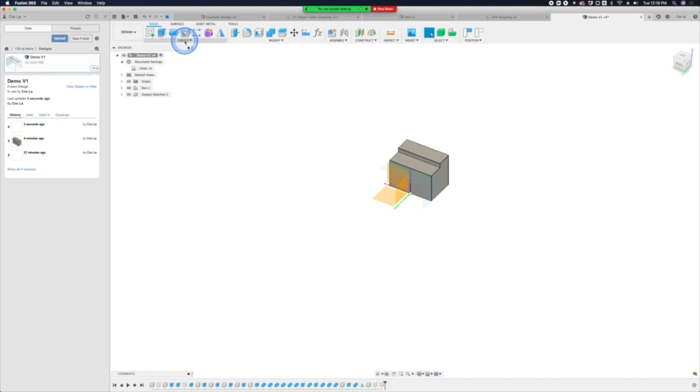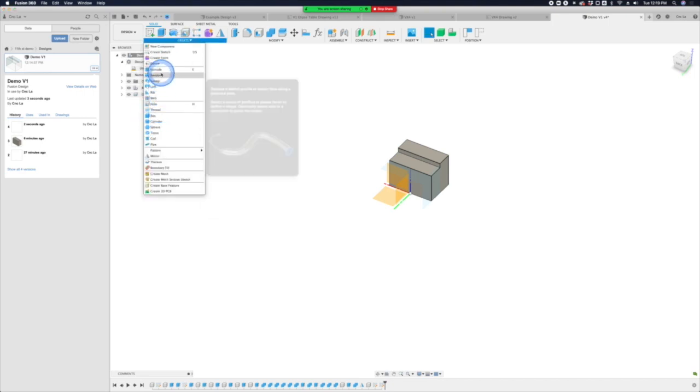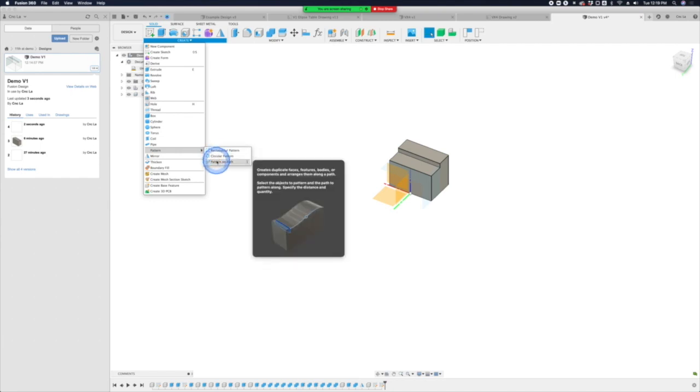You can also create a pattern. You can do a rectangular pattern, a circular pattern, or a pattern on path, which is super useful if you have, I don't know, a funky shape that you want a bunch of verticals aligned with, or ribs inside a contour. I use that a lot. Say you've got 1x3s you want to cut out of a curved shape so somebody can nail wiggle to it. I'll draw a 1x3, extrude it up, and then create a pattern on a path that cuts out all those shapes from a rib, and then we CNC that, and all our stuff fits together.